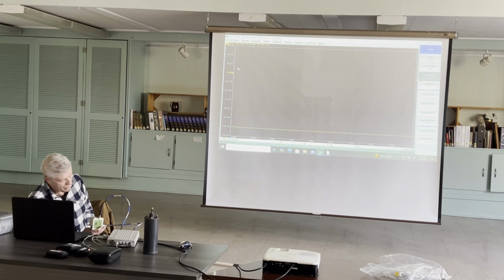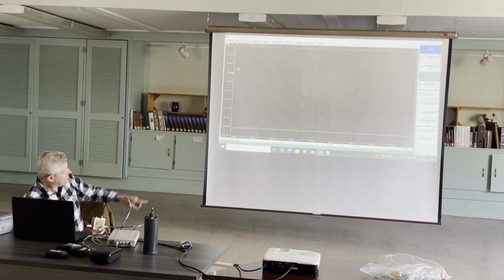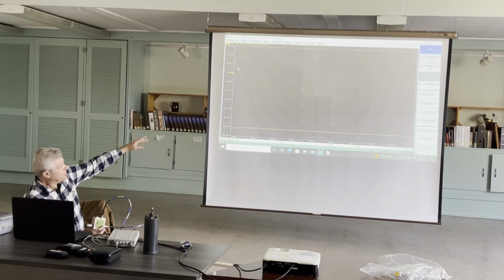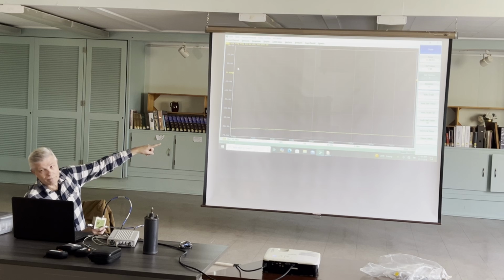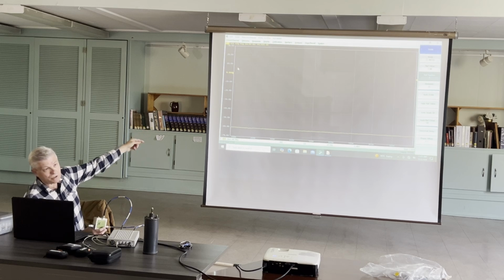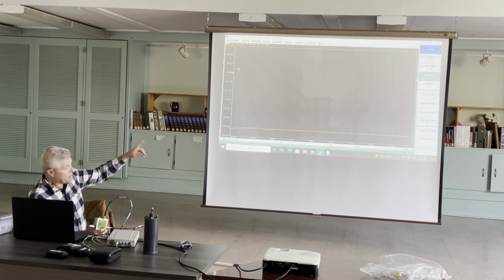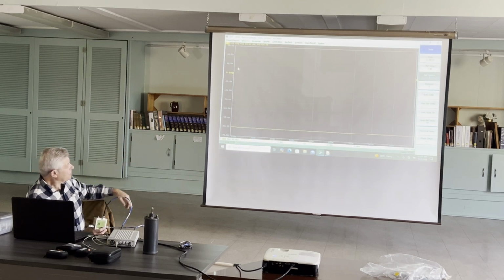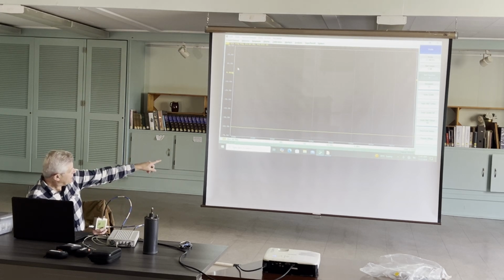Normally, in a coupling loop, there's a capacitive effect. And if you don't cancel out that capacitive effect, what do you think would happen to the coupling as you go up in frequency? It would increase, because the capacitive reactance drops as you go up in frequency, right? We use couplers made that way for a specific purpose because the directivity is better on those than on this type of coupler. But for power measurement, this is really handy to have.